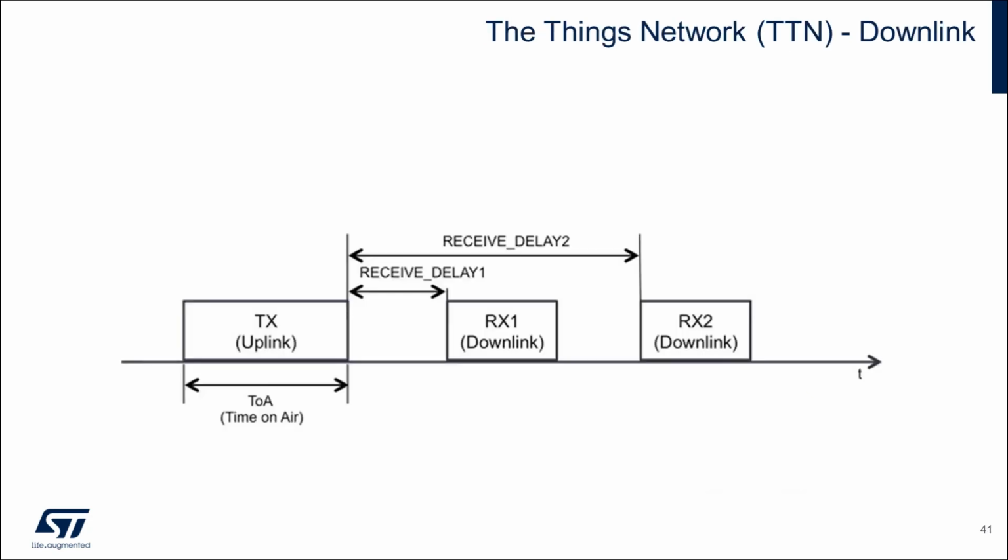By protocol definition, a Class A LoRaWAN device can also handle receiving downlink data packets. The protocol specifies 2 available downlink slots after each uplink event that can be used to send data down to the end node. I can demonstrate the downlink feature by sending a downlink packet from the network server console to command the end node to blink an LED.